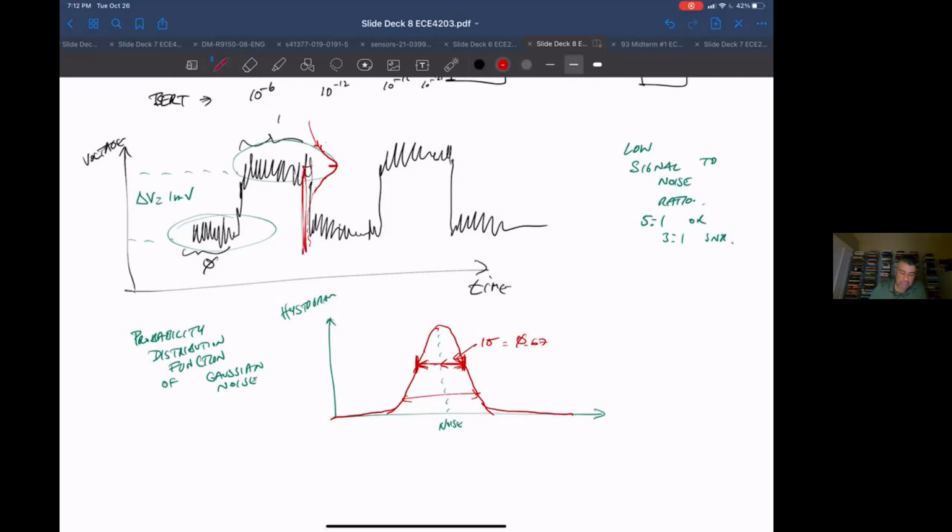That's the tail end of your Gaussian, where you're out 9 sigma or whatever it is. I don't remember exactly what 6 sigma or 9 sigma is, but 99.999 is within 9 sigma, which just means the next digit is outside of 9 sigma. So every once in a while, if you have 1 million events, there's a possibility you'll see a noise spike that's very large, larger than you expect, and it'll give you a bit error.